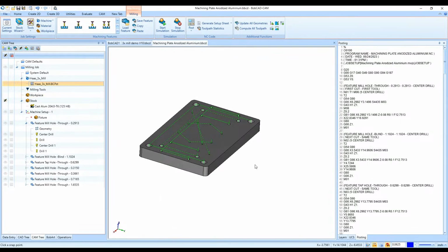And if we don't have the specific post processor that you need, or if there are any modifications you need for your specific machine, you can send us the post processor that you're using, and also send us a sample program that works on your machine. Send us a list of G and M codes and their functions, and any canned cycles that you're using, and we'll be able to do the post modification for you. That's included with support, from what I understand.